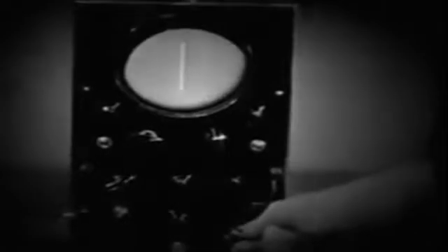Now, by means of the vertical amplifier control, we adjust the line of light until the pattern is the right size. Next, we adjust the horizontal amplifier to expand the pattern. This pattern is meaningless because the sweep rate is not yet synchronized with the 400 cycle voltage in the vertical plates. To synchronize the signal, we now adjust the coarse frequency control to the 400 cycle range, and then operate the fine frequency control until the pattern on the screen stands still, or nearly so, to give us a graph